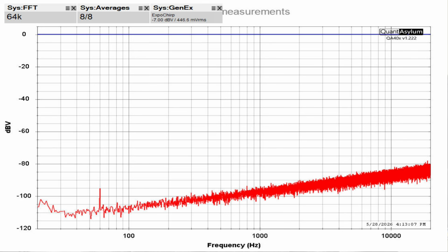The reason the noise shows up more than it would do normally is because the second channel input is open circuit, and it's just open to all the muck and stuff in the air. So it's worst case syndrome.